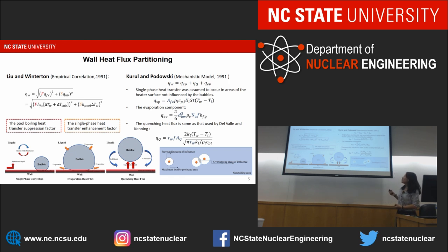This model has a better representation of the physics, but it also requires more detailed information about the boiling phenomenon, like the departure diameters, the bubble release frequencies, and the nucleation site densities.